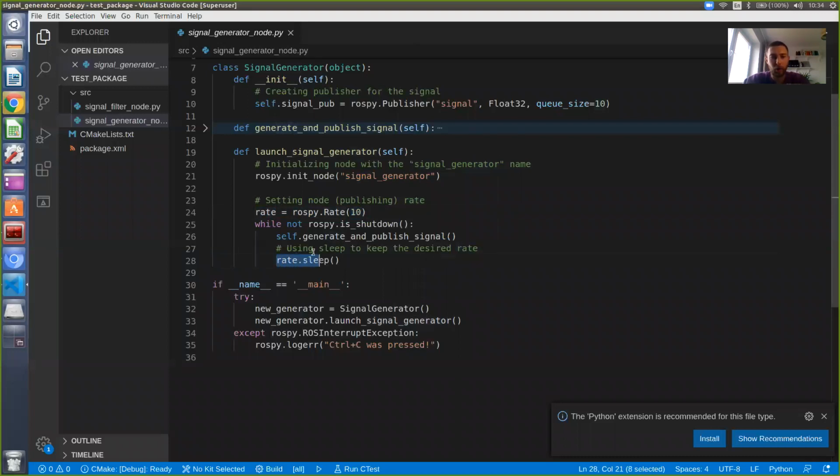And then we will call within our cycle, which is an infinite cycle. Actually, it is not infinite, but it works until ROS is shut down. And there is a specific function, rospy.is_shutdown, which checks if the ROS master is still working. And once it's shut down, this cycle also will shut down. Really convenient. So once you kill the master, you kill the whole ROS system if it's written in this way.